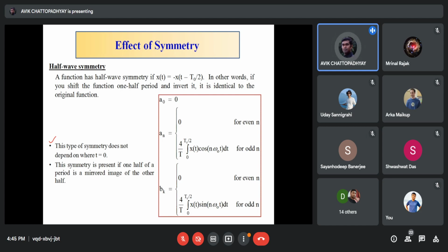This is because after a certain value of frequency component, or after a certain harmonic, it hardly matters whether you add more or not, because it's not going to change too much. More or less the approximation is a good approximation. We actually shared a picture where a blue colored rectangular waveform is approximated by some sinusoids. There we have shown that the more terms you add, the better the approximation becomes, but it doesn't mean that you will keep on adding terms for the rest of your life.